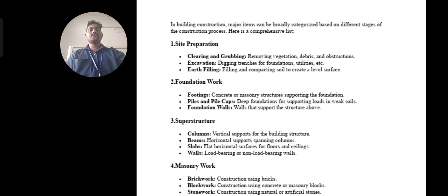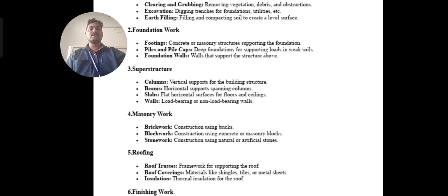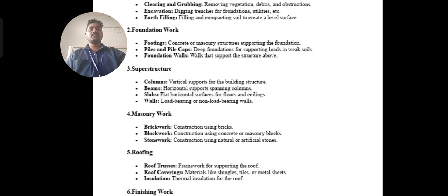And then we see the wall-related masonry works. There is brick masonry and stone masonry. So likewise we calculate the number of bricks and the number of stones required, the cost of bricks, and the cost of labor. And in the masonry we also have mortar, so that mortar is also going to be estimated here, and we calculate the quantity of it.